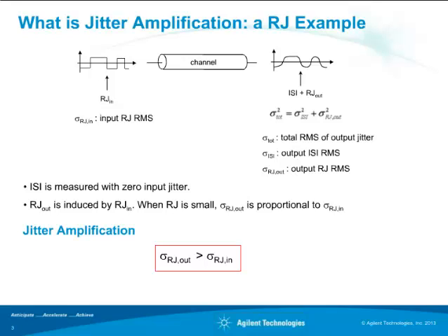And in these square waves, the transitions between 1 and 0 are modulated by the random jitter. And on the right of the channel is the output signal, and you can see the signal is being low-passed by the channel loss compared to the signal on the left.